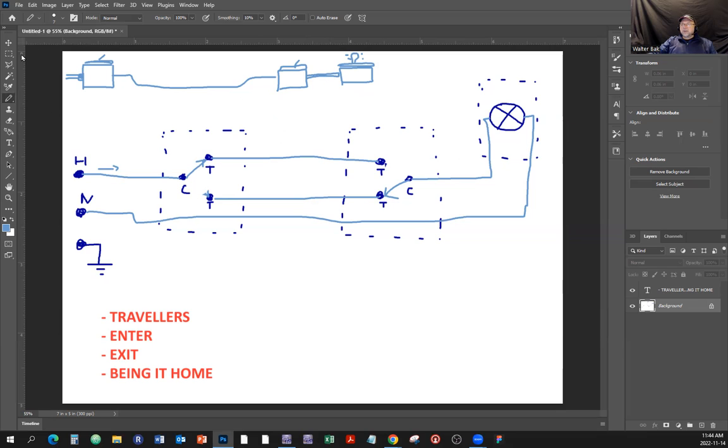All right, so how are we going to indicate that there's a conduit? We're going to just do it like this, just by that kind of elliptical shape here. So here's a conduit joining these two boxes, and here's a conduit joining these two boxes. Now, in here, there could be a conduit or not, depending, but we're just going to indicate that there's some wires going in here. All right. Now, over here, how many conductors do we need and how many conductors do we need? So we're just going to make a little reference marker. So here we're going to use 3 conductors.